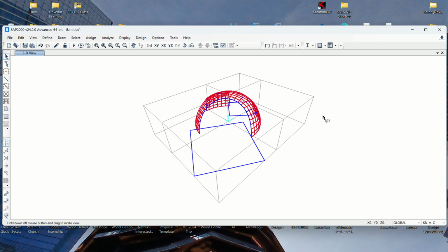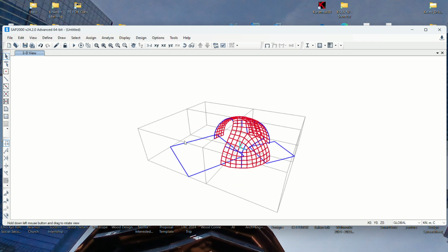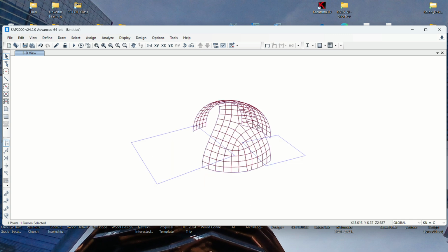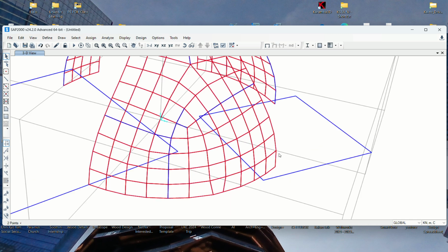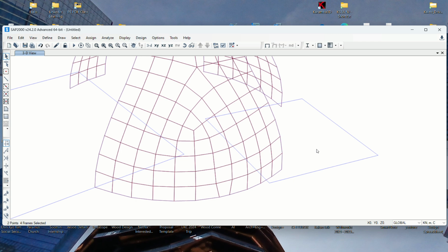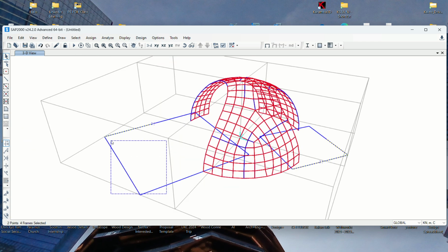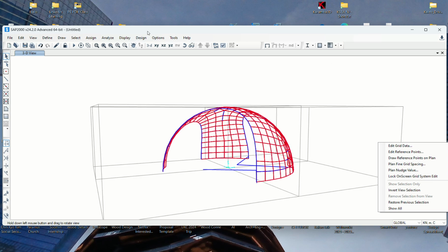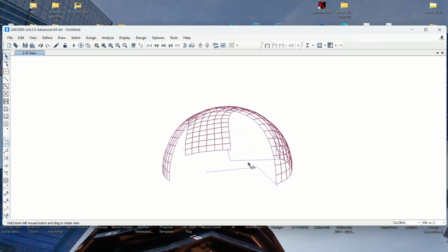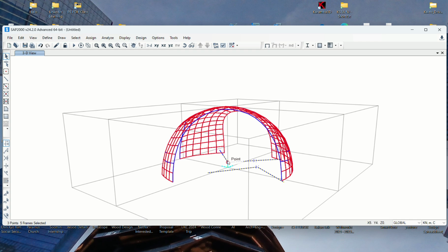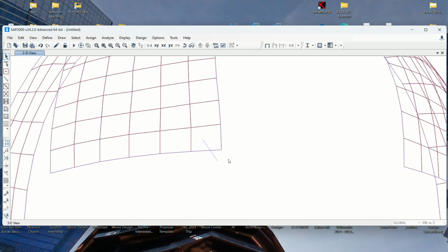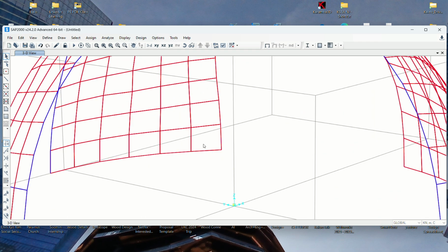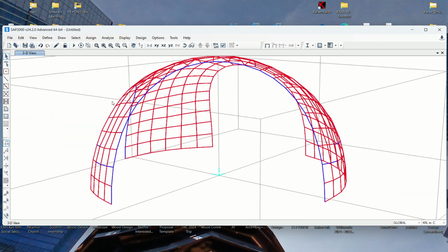Alright, so as you can see, I exported the circle, right? But a circle actually cannot be exported and translated, so you see some randomly chosen equivalent square, which I need to delete. Maybe I either export it or delete here, whichever is convenient. So delete it. Okay, delete all.